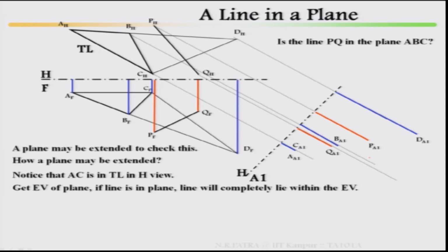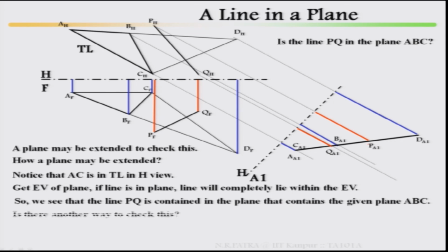Then get the edge view of the extended plane, so it will be a line, then extend that line PQ along the same plane and check. It is another way of checking whether a line is in a plane or not. Here the line is in the plane.